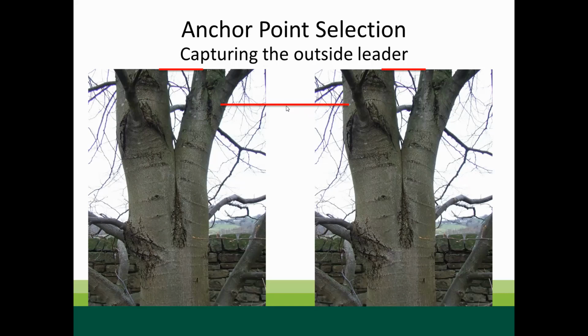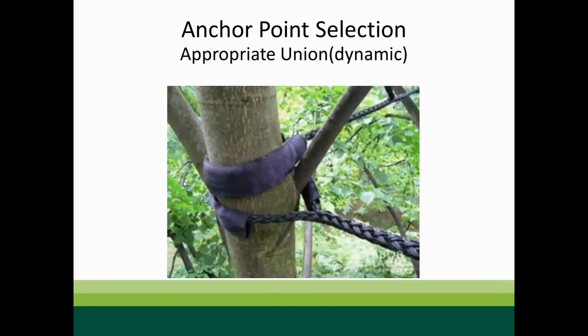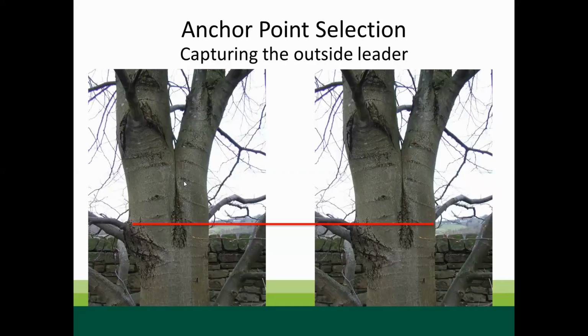If you can, that's why we have to think about 2/3, like maybe this is 2/3 height. We can't get so ingrained in, oh, it has to be 2/3. I'm going to get a tape measure out, because this would be a way better application for that cable if we could come below that union in there. And looking at it, not even like that one where it's so extreme where they're both across, if you can get through here and you have a clear path, get to the back sides of those. Even if they're nice unions, always come to the back sides, so you're compressing that union into itself.